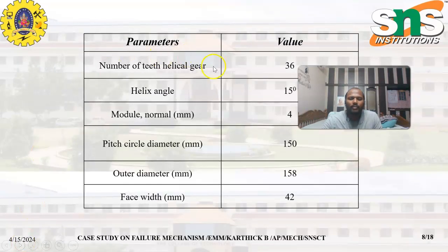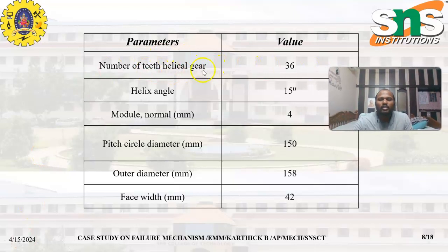Next, we are going to see the parameters. The first one is that in helical gear there are 36 teeth, 15-degree helical angle, module is 4 mm, pitch circle diameter is 150, and the outer diameter is 158 mm, and the face width is 42 mm.